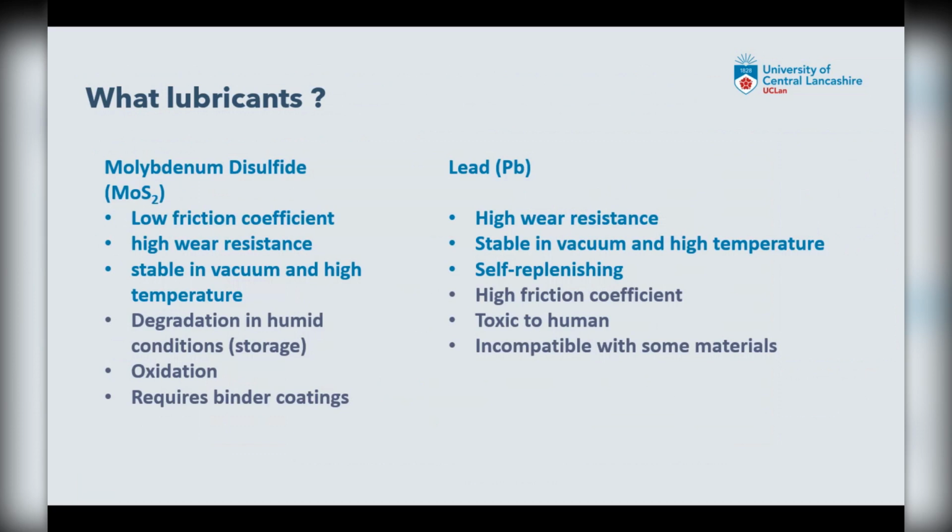It has low friction, high wear resistance, and is stable in vacuum, but it has a huge downside: degradation in humid conditions. Usually when the spacecraft is stored, because of the humidity in Earth's atmosphere, the lubricant starts to degrade and oxidize.